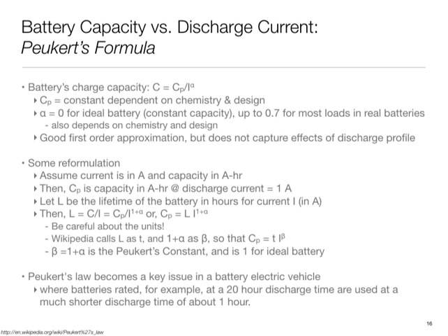These non-idealities are very important to capture in EVs, and certainly in grid scale things. Part of it is that in vehicles, your driving habits play an important role. For example, an EV would state a range, but if you use Tesla's ludicrous plus acceleration mode, for the same miles driven you're going to drain a lot more of the battery, because you're drawing at a higher current. That aspect has to be taken into account, which is why these vehicles offer you the rated range and a range that depends on your driving habits, and then they give an estimate.